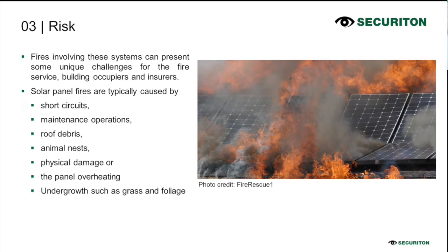If you've seen solar panels during the lines, when there is debris on top of the panels, certain parts get higher heat and certain parts get less heat, and it becomes a hotspot area due to the non-uniform power redistribution. When this non-uniformity happens, there is a chance that fire can be triggered on the PV cells. This was also documented recently in one of the fire incidents, and it can also ignite nearby flammable materials if they are there.